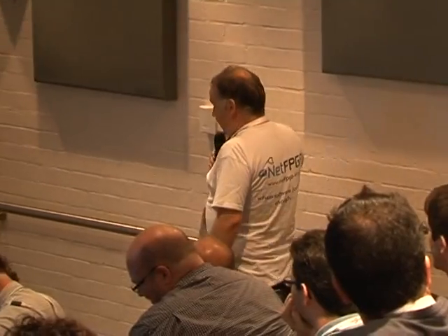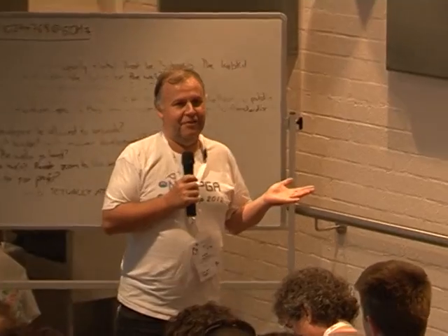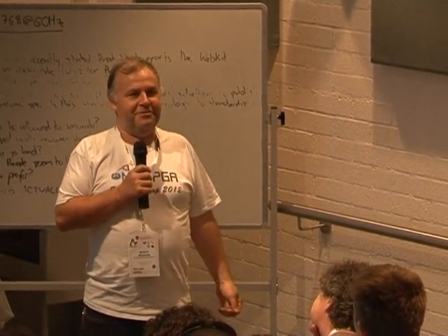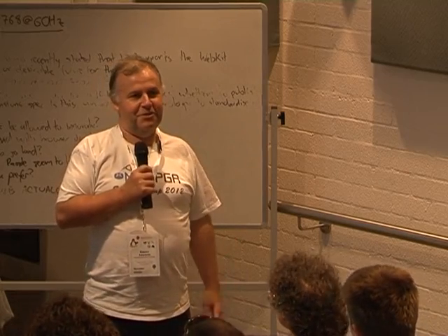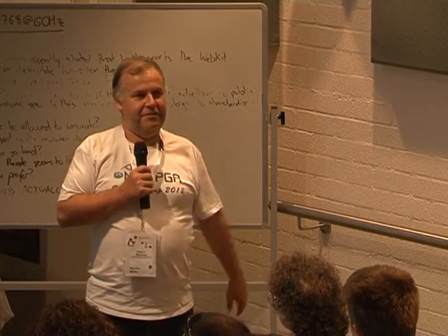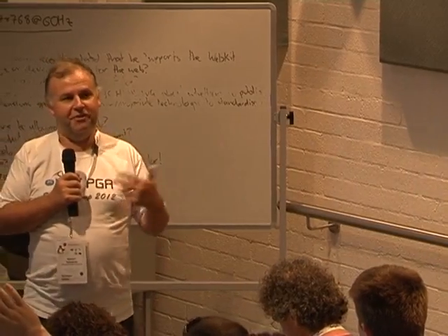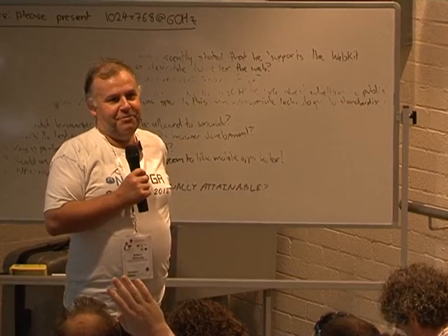Well, I'd be really wary of calling any of the people in the FPGA team twits, but I've never seen anything that uses the debug connector. The debug connector is just there, and I've never seen a single reference to anyone doing anything at all with it in terms of presenting information. So they may have used it internally just to check that things are working right, but it's got ground, so there's 6 ground pins. It's got 2 clocks that control the FPGA. They're called clocks, but I think they're no different to any other pin, and there's 32 other pins.